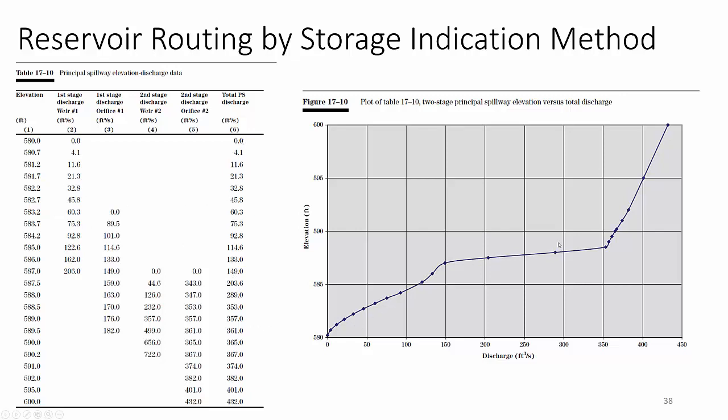And you see the cumulative discharge takes on a completely non-linear relationship based upon these cumulative discharge designs. This is the fun part of engineering, when you get to design these systems and stack these things in at different elevations or stages and say, all right, we want to drop more water once it hits. We can't let water get to 610 feet, for example. So when water gets to 588 or 587 feet, we're going to put in another orifice, and it's going to create another culvert that'll create another discharge rate.